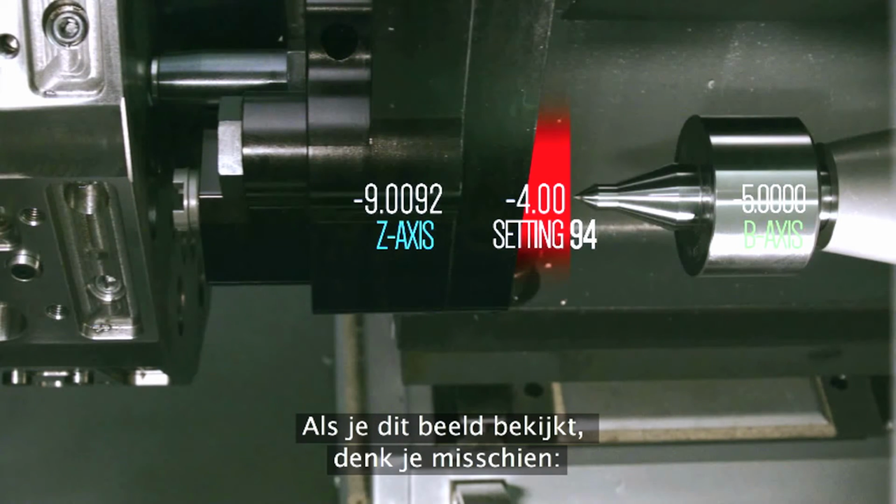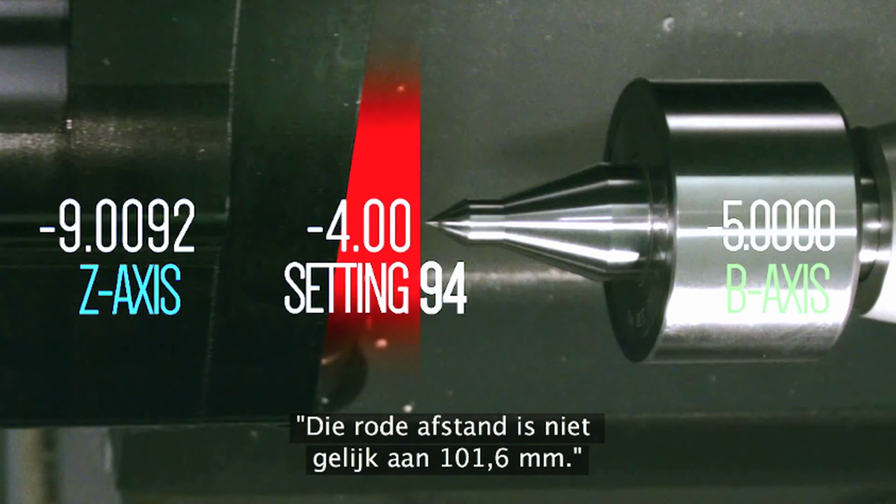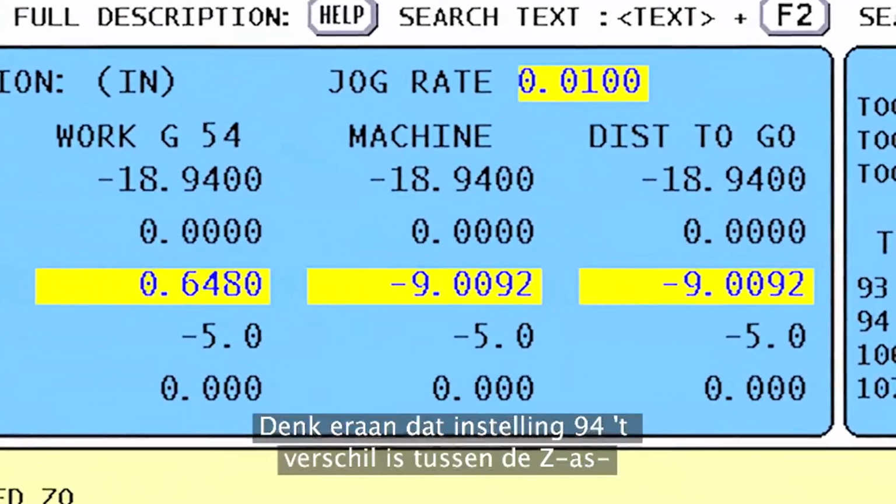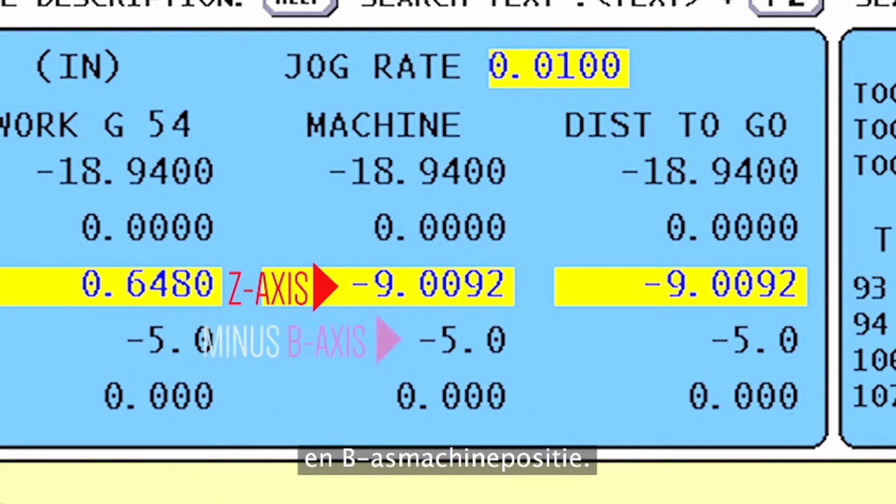When you take a closer look at this graphic, you might say, well, that red distance is obviously not 4 inches. Remember, setting 94 is actually the difference between the z-axis and the b-axis machine positions.